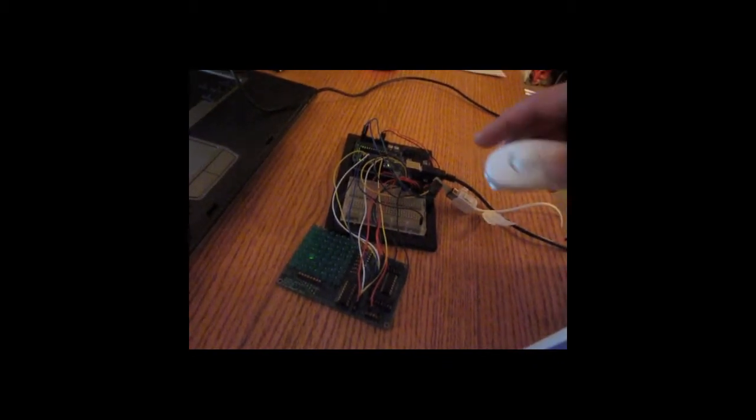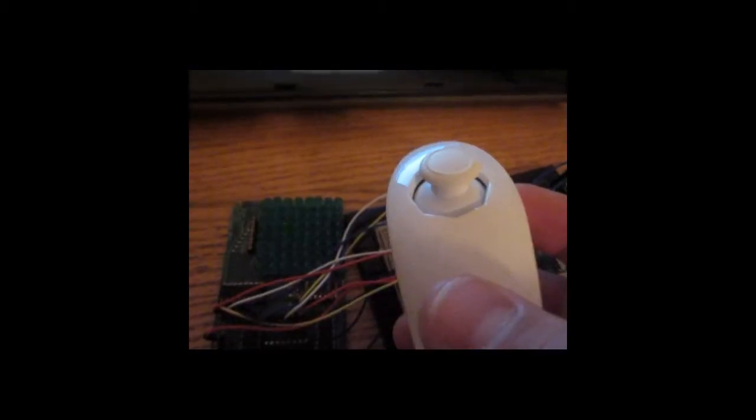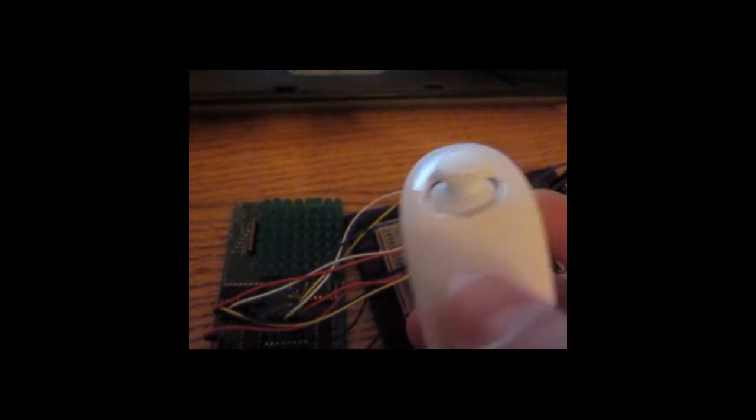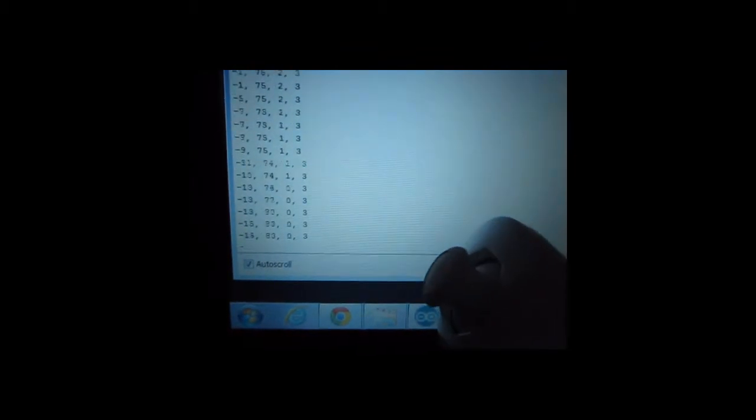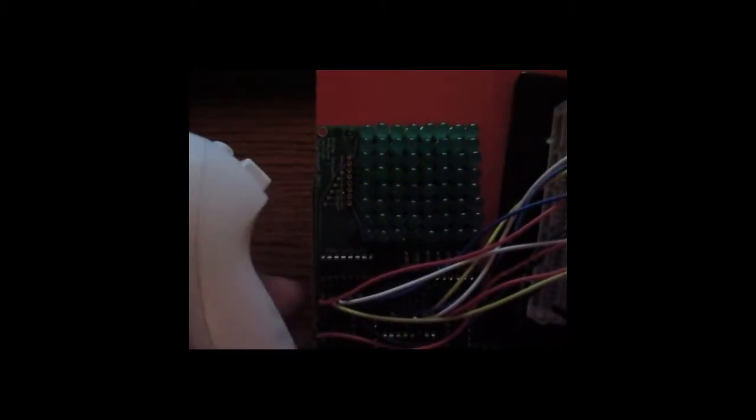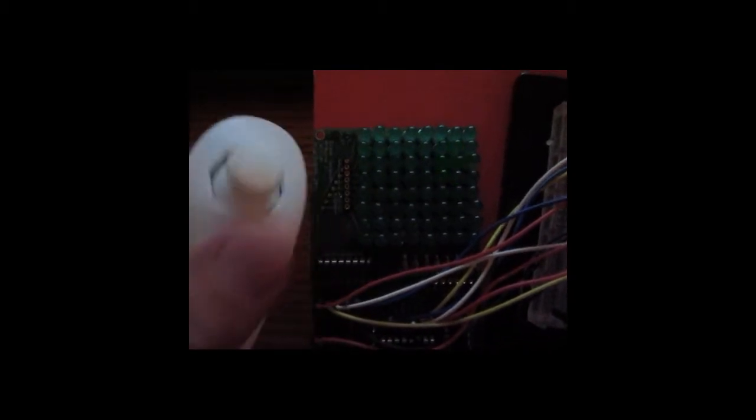Well, one thing I would do is try to find some way to increase the dwell time per pixel so the light output is brighter. Maybe I would use a different multiplexing scheme instead of a serial shift register, maybe some other kind of tool. Basically, I wanted to get the duty cycle up, because the reason they're dim is that the duty cycle is rather low for the persistence of vision phenomenon to work. Alternatively, I could use brighter LEDs, and they are made. They just wouldn't fit on this printed circuit board, not in the current implementation.